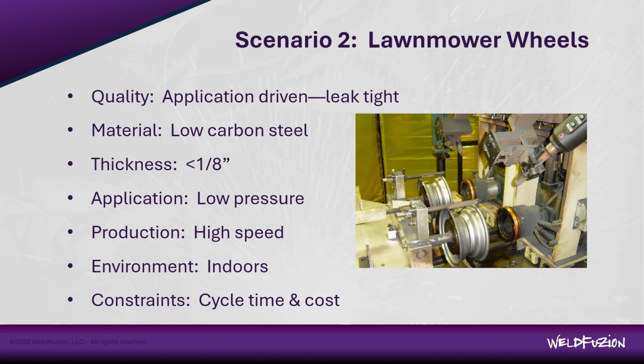We don't want to deal with a lower efficiency wire that's going to take more time to clean up, right, due to that flux and slag. And TIG would be way too slow, right? We know TIG would work, but we don't have the time to wait for TIG to get done. Yes, this here is a classic MIG welding application.